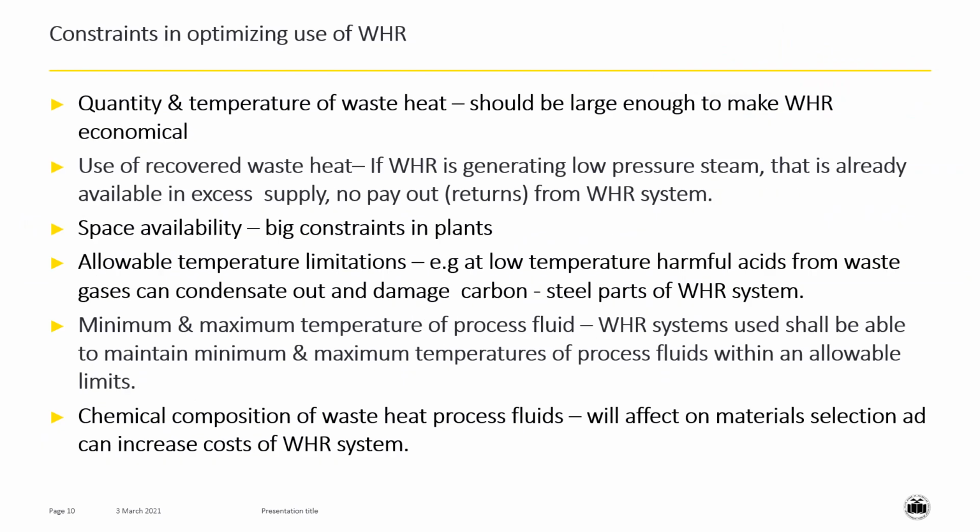There are certain constraints in using waste heat recovery. First is quantity and temperature of waste heat. It should be large enough, otherwise waste heat recovery systems will become uneconomical. Use of recovered waste heat: if it is made for generating low pressure steam that is already available in the plant in excess amount, there will not be any returns from the waste heat recovery systems.